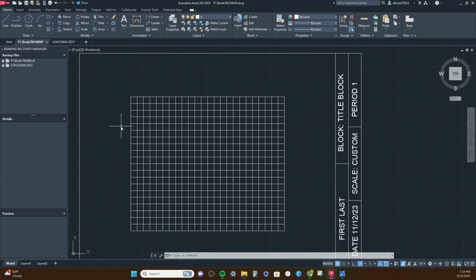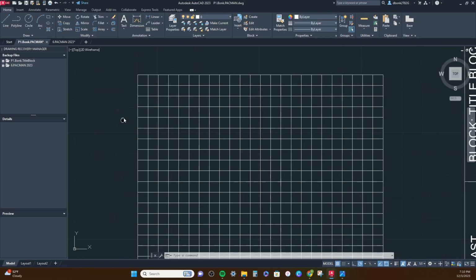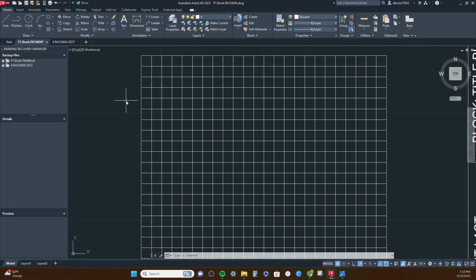So just try and slowly get yourself set up. Zoom in like I am here. Hit the trim button. Count 1, 2, 3, 4, 5, 6. And on the 7th, count in 4. Drag with the trim tool. You just hold the left mouse button down, and it'll trim through those.